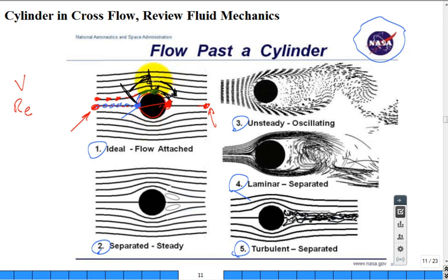We compare the pressure. Is the pressure right here high compared to the pressure right there? The second one, the one on the backside. Isn't that the higher pressure? So you've got flow slowing down, moving to a region of high pressure. Let's compare the front half.